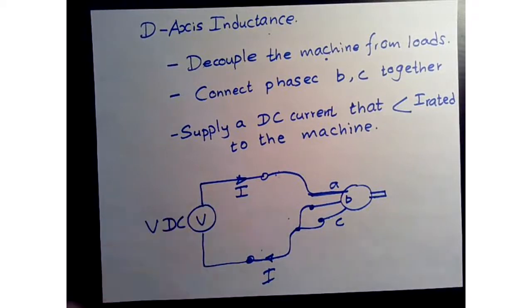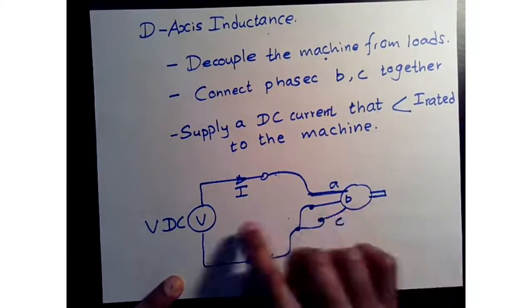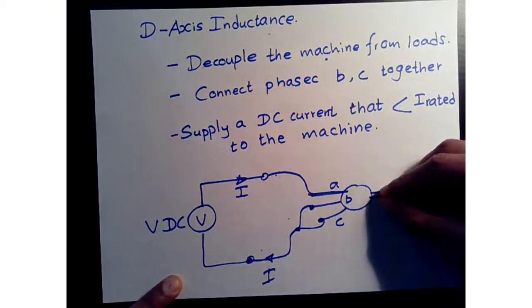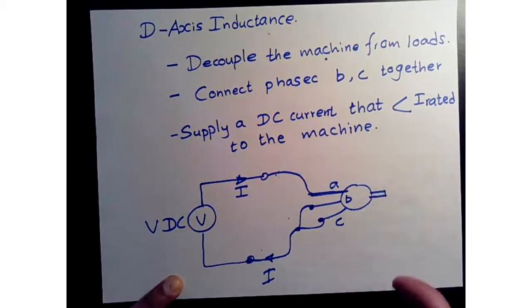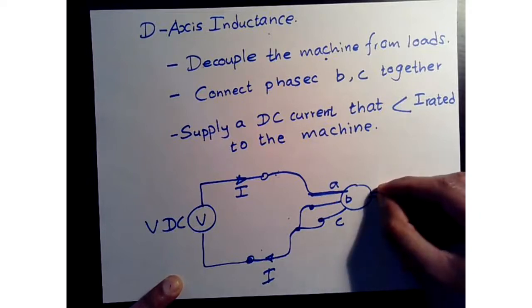This is basically applying the voltages. Now at this point, once it's aligned this way, you can lock the shaft. You'll need some other means, another machine or a wrench or some kind of physical mechanism to hold the shaft in a stall condition.